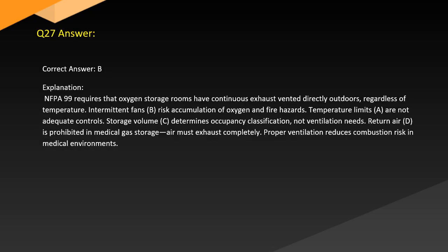Answer. Correct answer: B. Explanation. NFPA 99 requires that oxygen storage rooms have continuous exhaust vented directly outdoors, regardless of temperature. Intermittent fans (B) risk accumulation of oxygen and fire hazards.